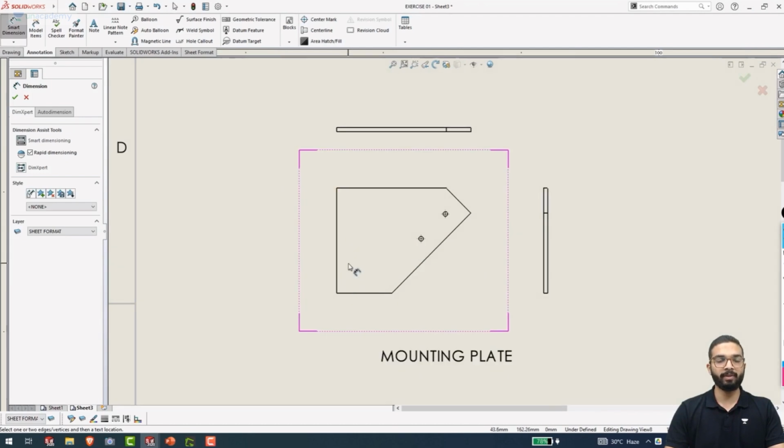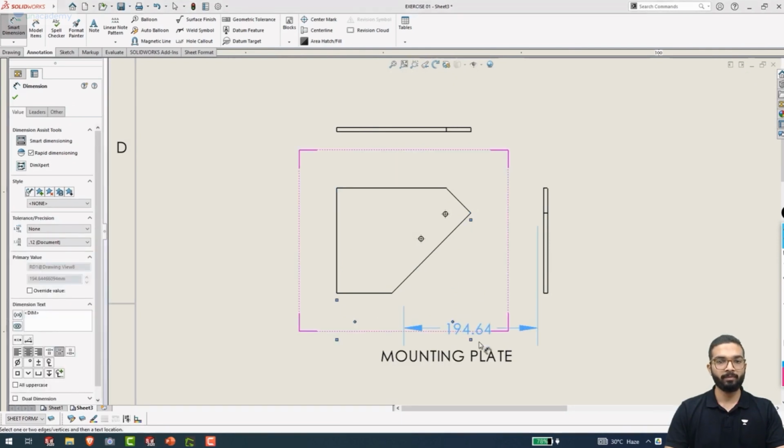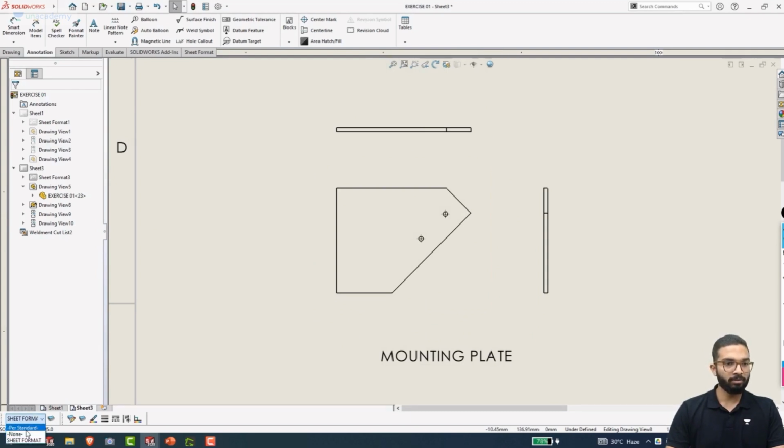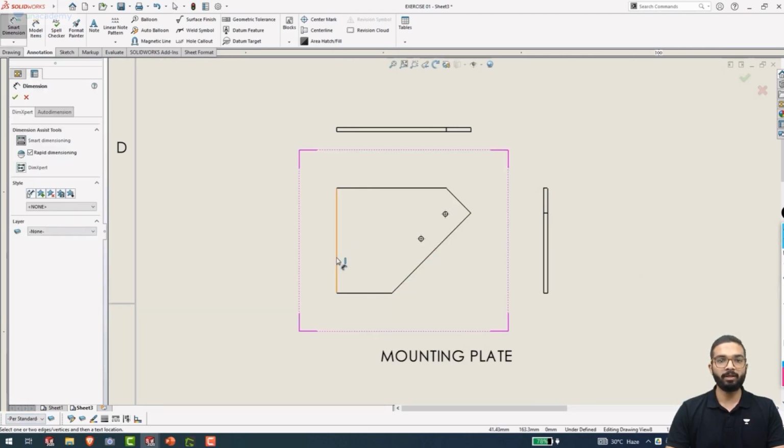I will get into the Smart Dimensions tab. I will go here, specify this length over here. There is some issue. I will delete this, select this, delete it. Okay, I am into the sheet, that's why it is giving me the issue. I will go to, let's say, standard sheet. I will get into the smart dimensions command and then now give it a value.